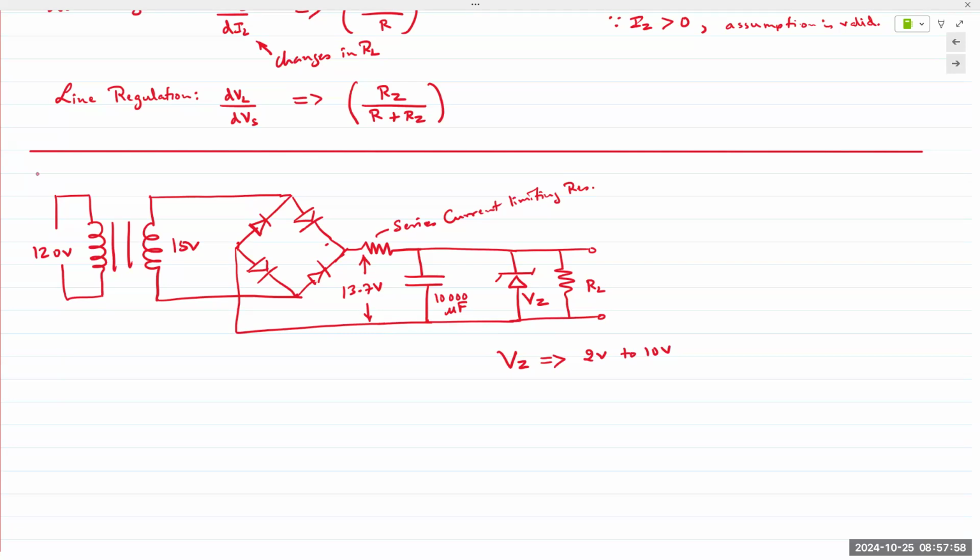And remember, we had the equations for the ripple voltage in the filter capacitor, right? Depending on the size of the ripple, we choose a filter capacitor. All of that is taken into account when you're designing a power supply. But this is the bare basics. If you want a quick and easy design, this is something we can come up with.